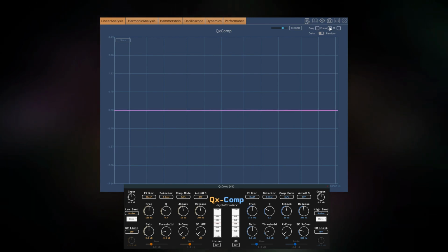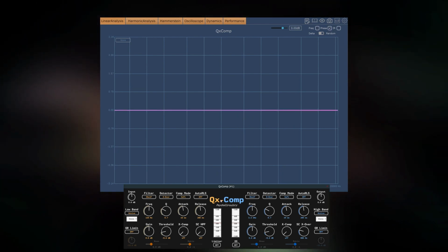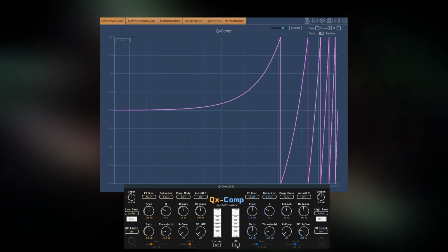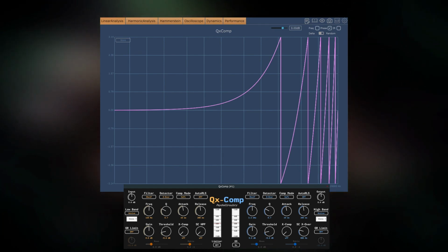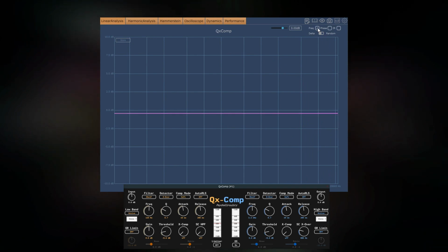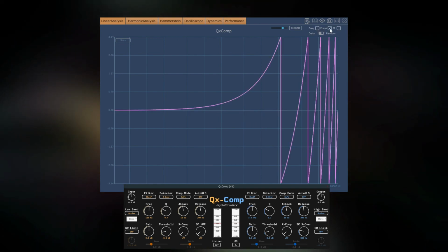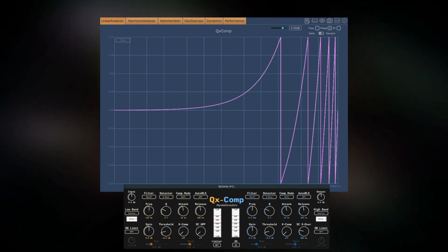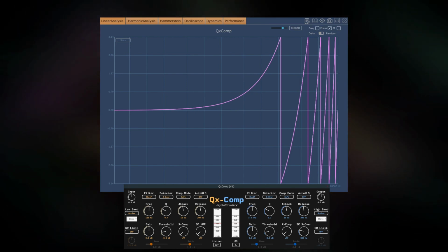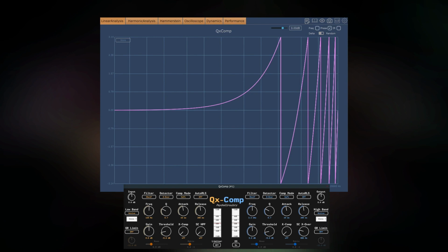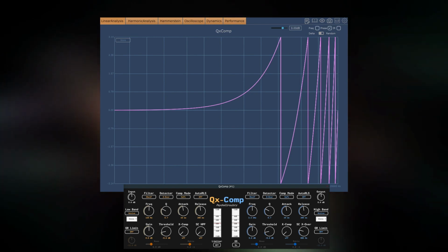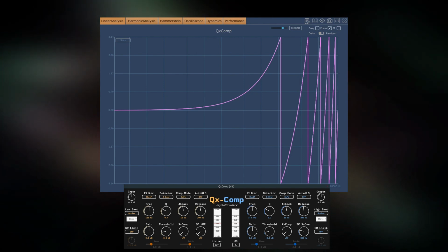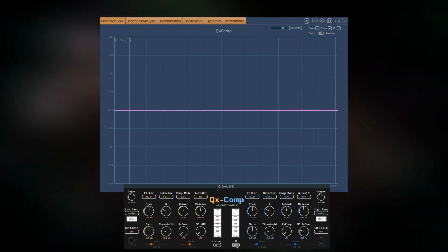When we look at the phase, we see no deviation when oversampling is disabled, and when we turn it on, we see some kind of strange phase response on the upper half of the spectrum. This is because the oversampling employs a polyphase design, not a linear phase design, which creates some phase discontinuity throughout the signal, but had a more defined upper frequency response than the linear phase methods that were looked at for this plugin. Well, at least to my ears.